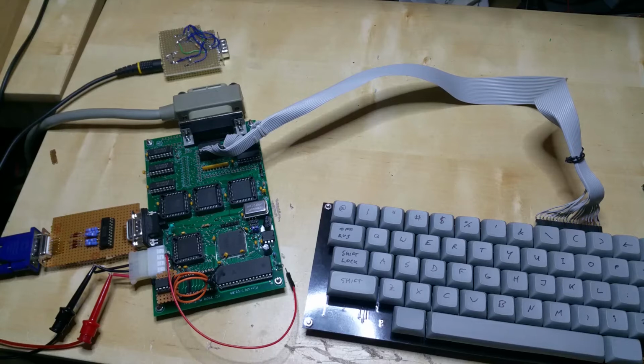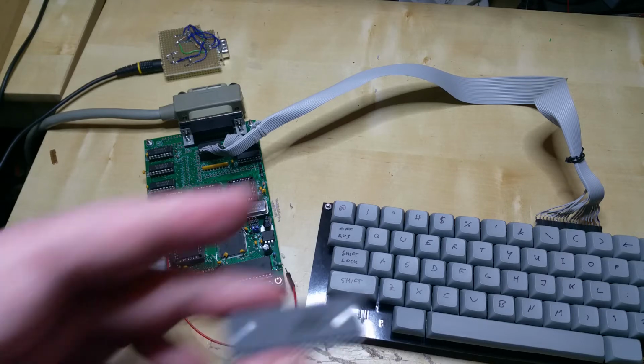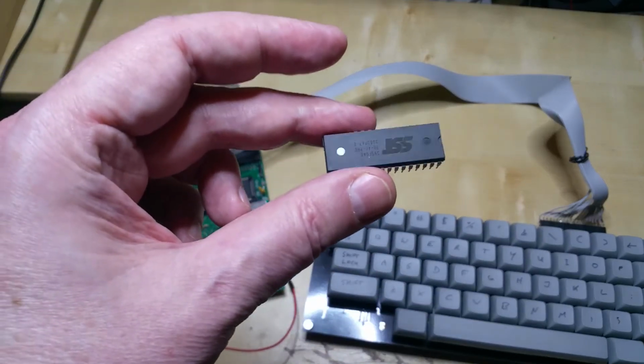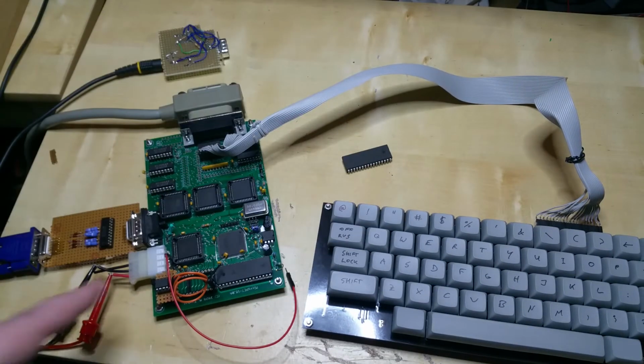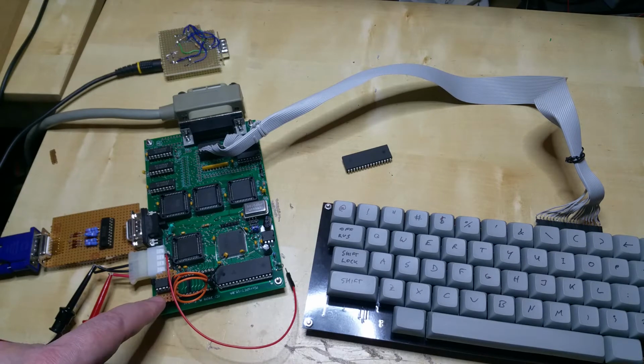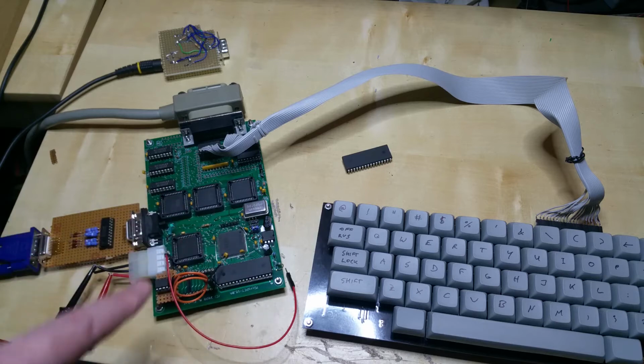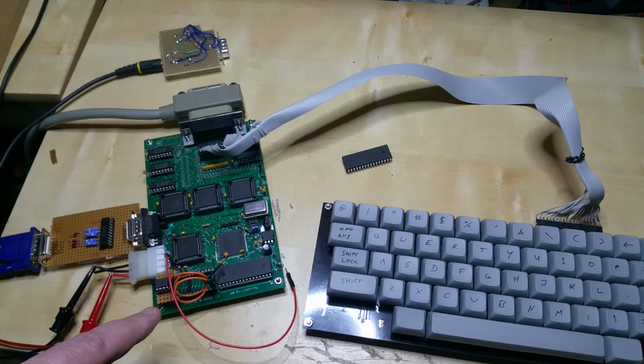I've continued working on the MicroPET and the Flash ROM boot functionality. As you can see, I have succeeded to fit everything into the CPLD, and I have replaced the parallel ROM that was used to boot before with a much smaller SPI Flash here on the board. And I have been able to fit all the bootloader code into the CPLD.